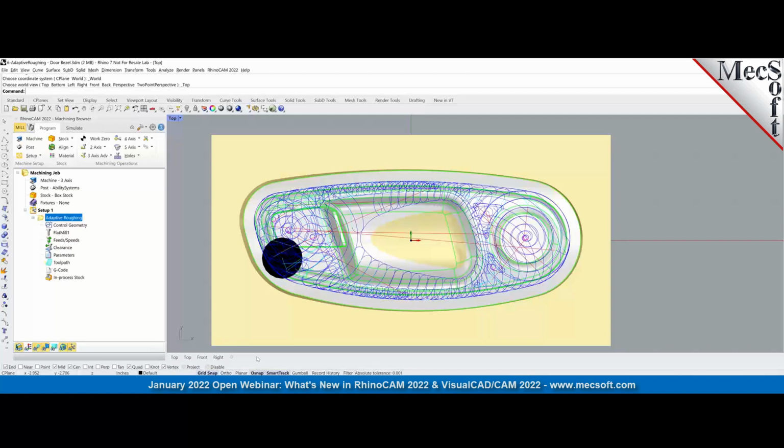We can't import it, but you can import it as a model and then measure the parameters of that and then input that. So basically, the way you create it, as you saw in the holder definition, was segments. You're creating either cylindrical or conical segments. Those are the things that you can do now. Similar to user-defined tools, at some point we'll be able to bring in a curve, maybe a surface of revolution, and then use that as a holder, but not in this release. In this release, you can only do cylindrical or conical segments.